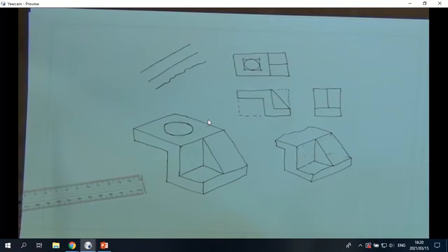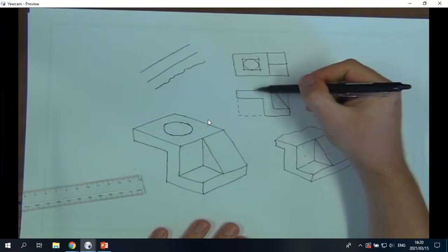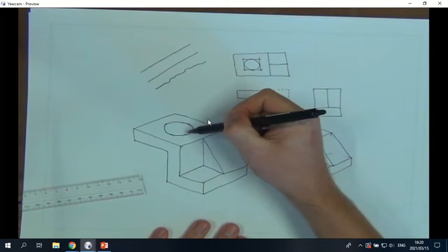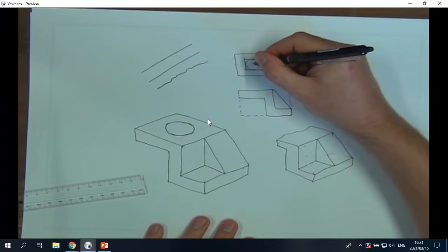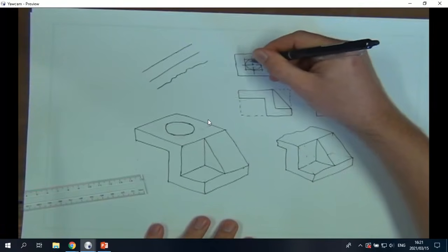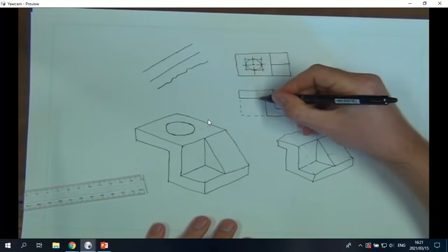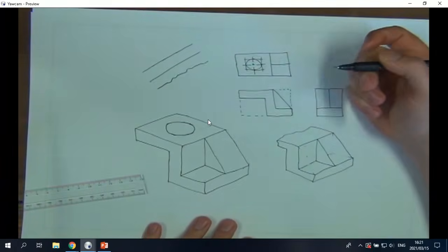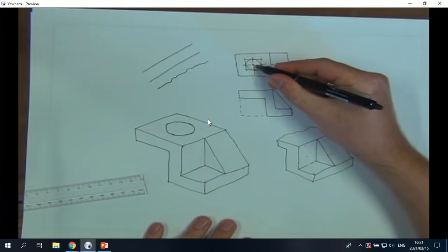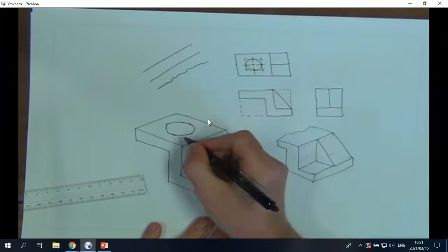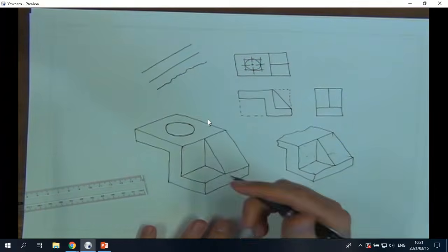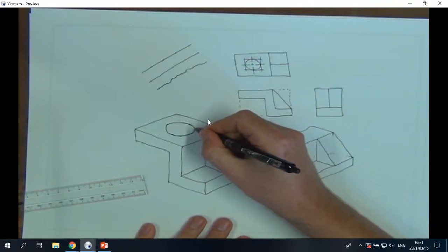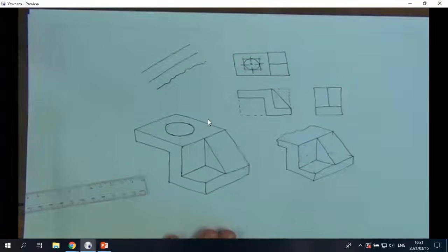Now, there's an interesting question. Would we see the arc in the bottom? So basically the other side of the hole. Now the rule is basically if the radius of the circle is bigger than the thickness or length of the cylinder, then you will see it. In this example's case, it is exactly one block and one block. So that means the bottom circle will actually just touch over there, so it won't be visible. In other examples, you might have a circle visible over there or not at all visible.